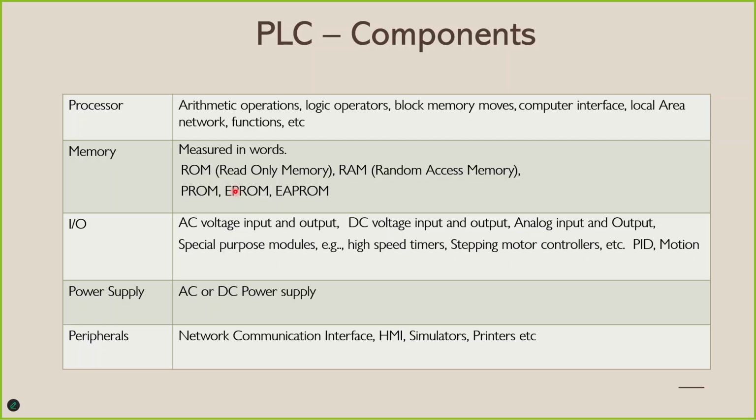So the ROM is the read-only memory, in major electronics, one of which is a PLC, where you only have access to read data from the device. Here we store specific manufacturer software, or I would say the operating system of the PLC itself, just like your laptop, the operating system is usually on the ROM. And when you switch it on, this is the part that usually comes into play.